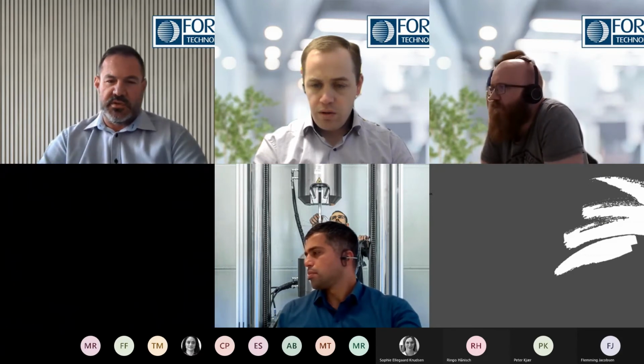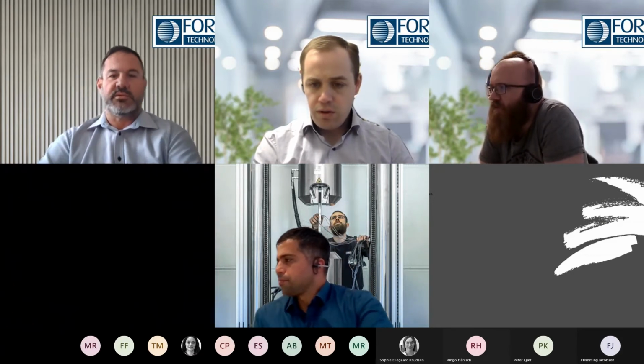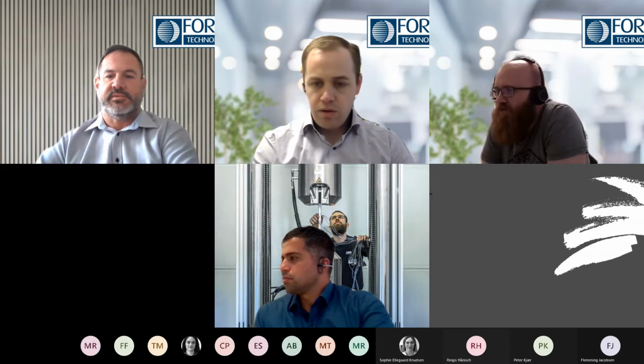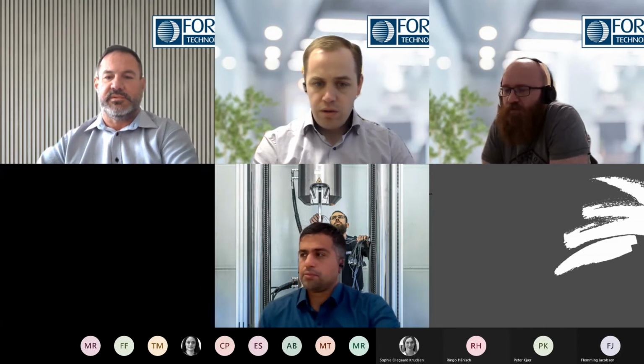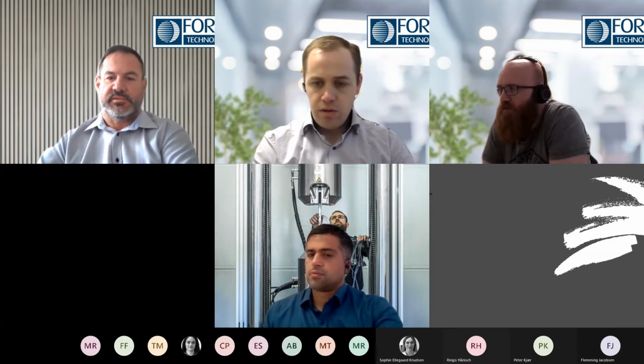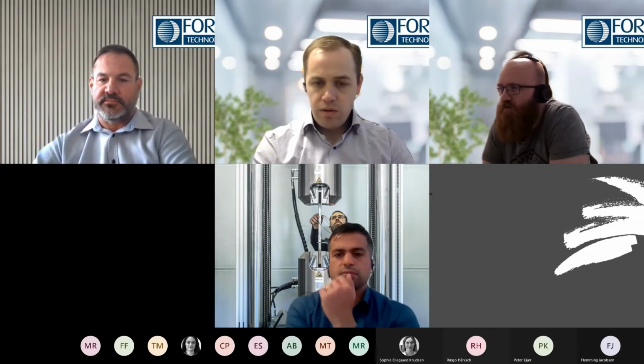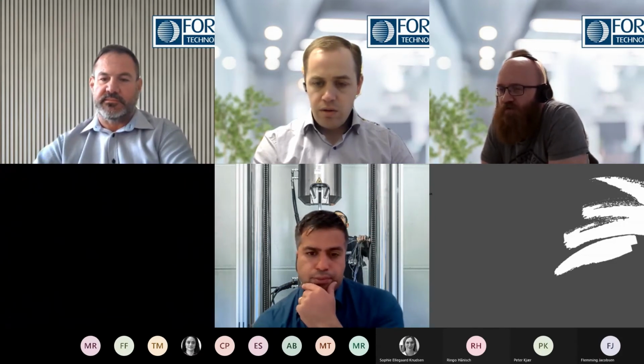I can take the one for the fracture toughness, whether it's better to increase the size of the specimen until getting it through E399 or to switch to E1820. I would say that very often it becomes very difficult to get valid results in K1C testing at room temperature or 0 degrees Celsius.